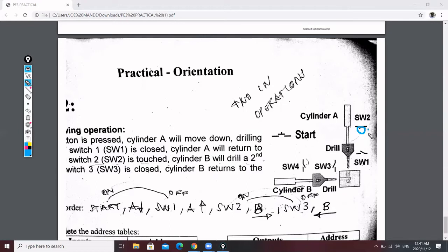When it starts moving away, there is no weight anymore on 2, which means switch 2 will open. And if switch 2 is open, when the weight reaches the maximum depth, switch 1 will close. So that's how it's playing around. Even from this side it's the same. The weight moves from the left to the right, from the right to the left, and that's it.